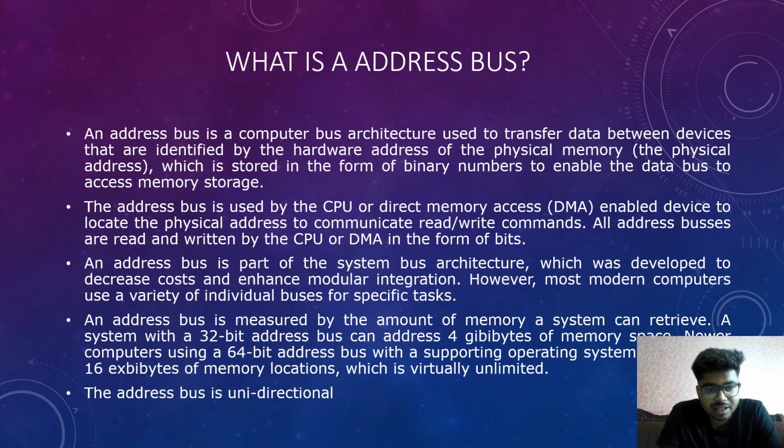A system with a 32-bit address bus can address 4 gigabytes of memory space. However, computers using a 64-bit address bus with a supporting operating system have 2^64 bytes of memory locations, which is virtually unlimited. And the main point is the address bus is unidirectional.